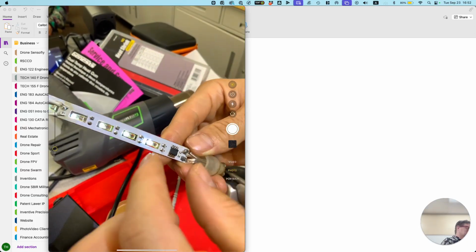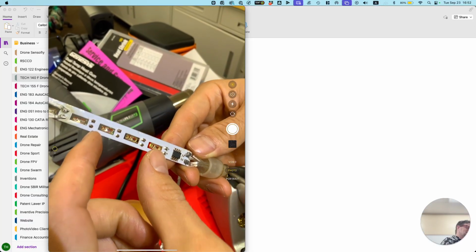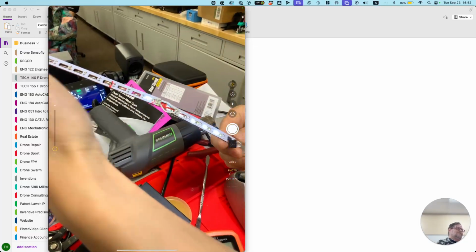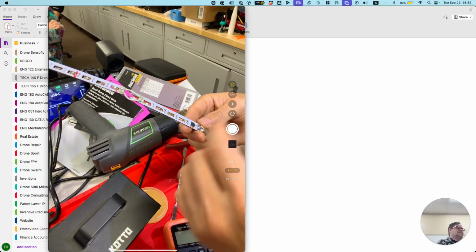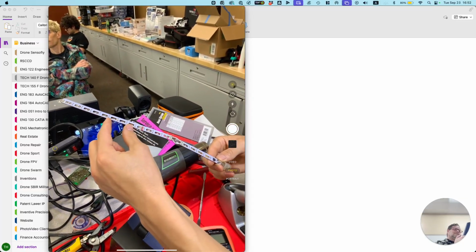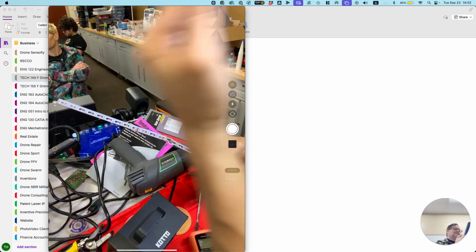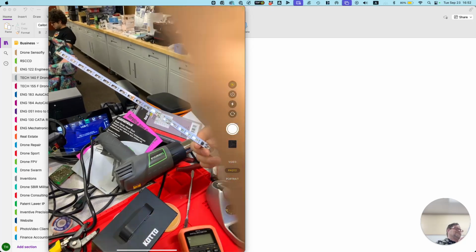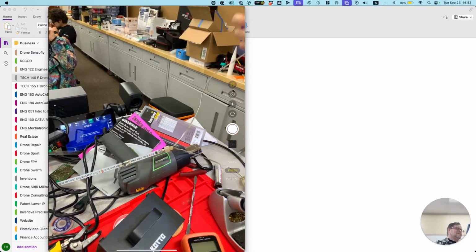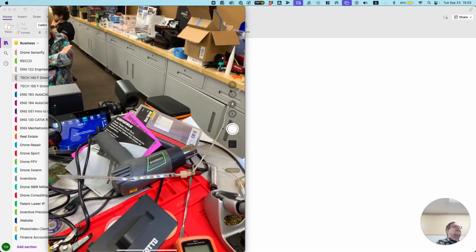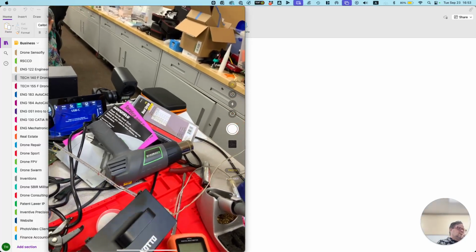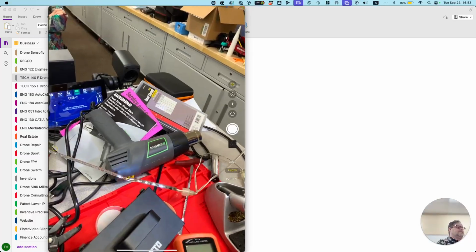It says distribute electricity to segment 1, then wait 100 milliseconds. Distribute to segment 2. So I'd tell you, the amount of LEDs in here is probably a multiple of 3. Let me see. 3, 6, 9, 12, 15, and 18. That makes sense. So basically there's 6 segments and it's telling segment 1, segment 2, segment 3, segment 4, segment 5. That's how it can create a cascade effect. If it was what we were hoping, just a simple series circuit, it would only flash everything at once.